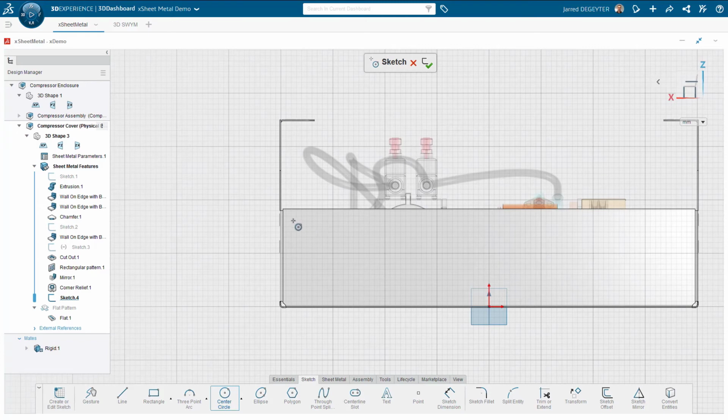But what you can do inside of these X apps is leverage something called machine learning. So I'm going to click right here on suggestions, and it's actually going to suggest to me, based on similar geometry, where I might want other sketch circles to be for me. So this is super powerful stuff. This is some advanced AI that's happening, and the great thing about it is that it gets better the more you use it. And you can even come in and modify and show similar drop locations. And this is actually what I'm looking for right here. So I want those sketch entities to propagate right there, and now I'm done with it by using some advanced machine learning. Super cool, super powerful stuff right here.